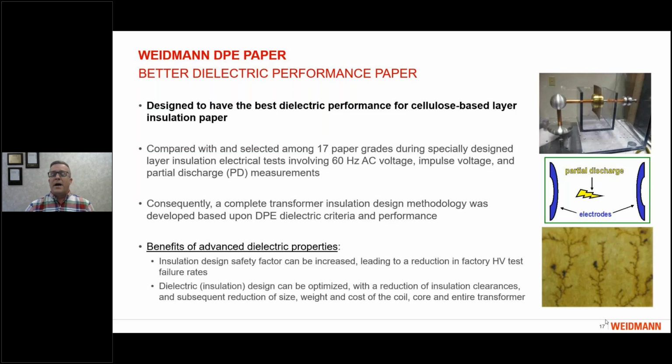And so the combined results of this study, looking at PD inception, AC breakdown, and impulse breakdown, is that we developed a special set of insulation dielectric design rules specific to DPE, which we can bring to our customers to help with their dielectric design. And so there's the potential to reduce clearances and to ultimately optimize size and cost due to the improved dielectrics with DPE.